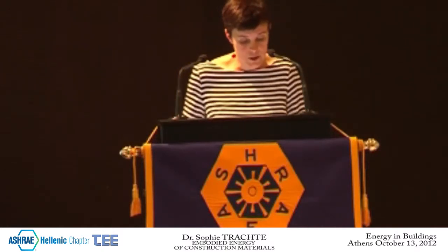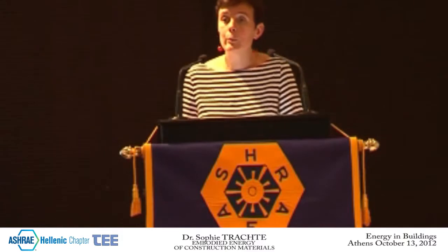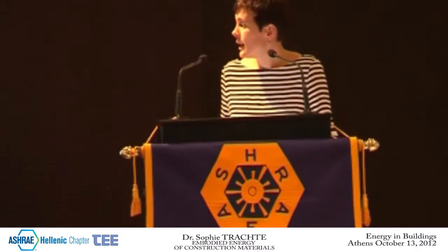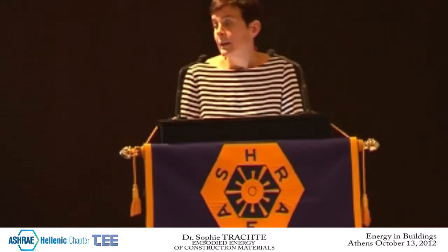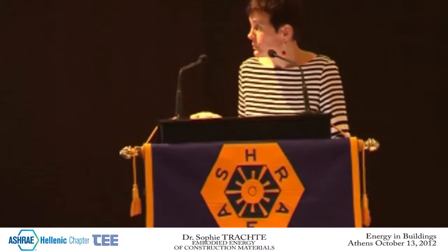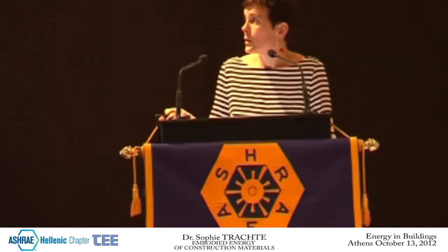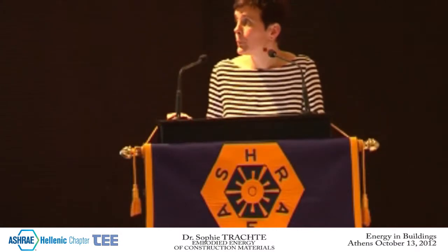And to finish my presentation, I would like to introduce a more practical example. First of all, I would like to make a comparison between different blocks: concrete, terracotta, and cellular concrete. Those blocks are integrated in a wall. It's important to assess not only each material by itself, but to assess a set of materials assembled in a wall. So we could also compare the physical or technical performance. The three walls have mainly the same thermal transmission. You could see there are also other technical aspects like thermal mass and acoustical performance.